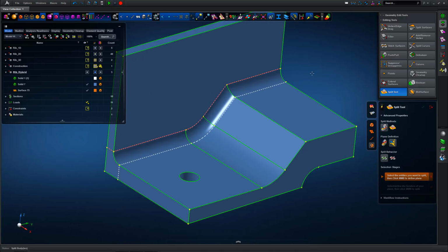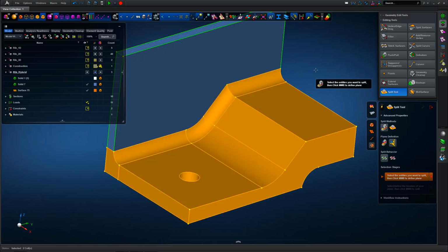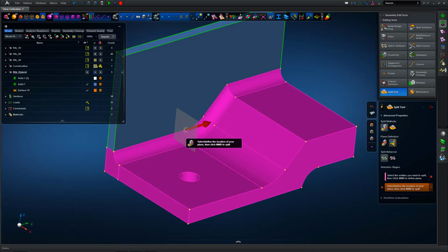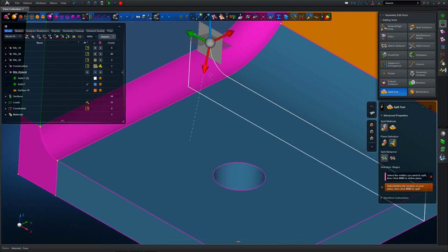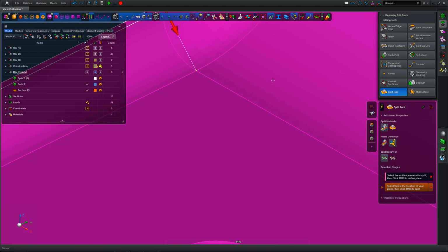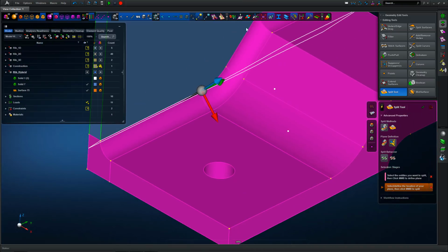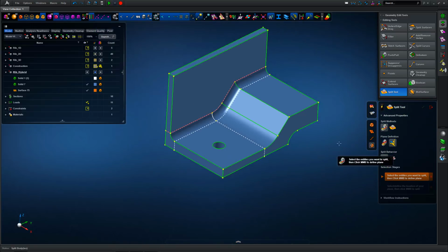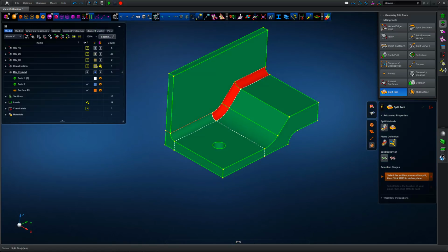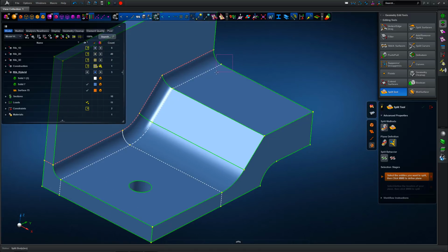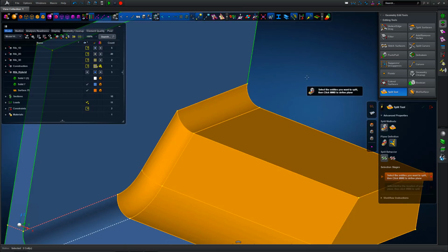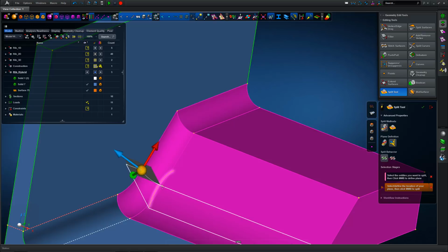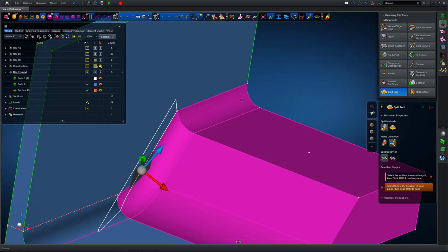So second split there, we can see we're still not mappable for this lower portion, but if we start to split in a sort of chordwise fashion now, as we make these splits, the geometry becomes mappable. And again, just making sure we pick the appropriate vertices. You have to be careful not to pick edges near vertices rather than the vertex explicitly. So those breaks now, we're chopping out the fillet from the overall solid. So effectively we now have more and more partitions of the structure shown in green as opposed to red, which means they're now mappable and we can hex mesh them.